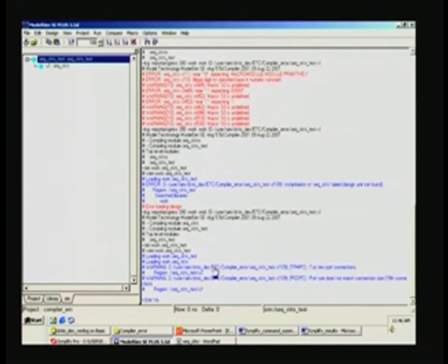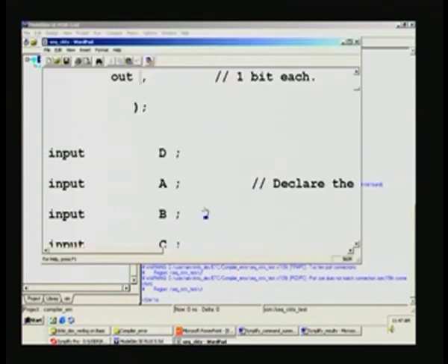So, if you click on this, normally the source file must be opened if it is a relevant message, right. Too few port connections, you will have to find out why, because we have put a comma there, it was expecting more ports to be listed. So that is why I think it is reporting too few port connections here, and in one more it says port size does not match connection size. But it does not open the 15th connection. Okay, 15th connection, let us see the source file.